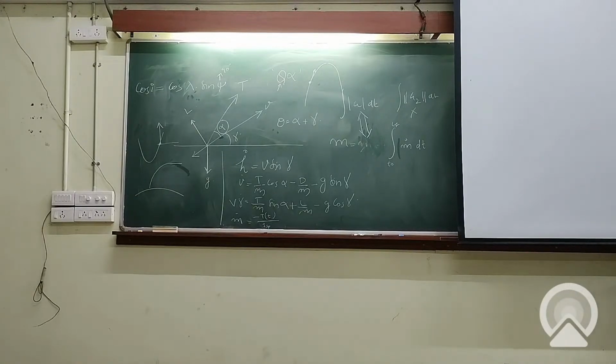Then we depend on direct methods, otherwise called transcription methods, where we make use of collocation techniques. It is basically reformulating an optimal control problem into a finite-dimensional nonlinear programming problem. So from an optimal control problem, it becomes an optimization problem. There you can apply all kinds of optimization techniques to solve the problem. Those are various aspects of solving the problem.